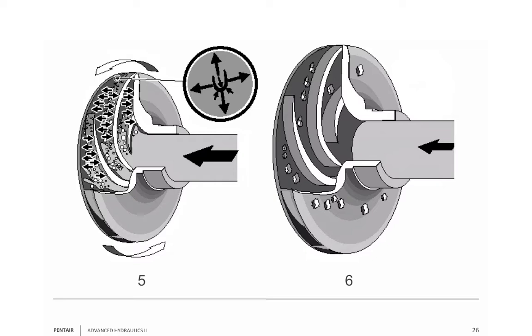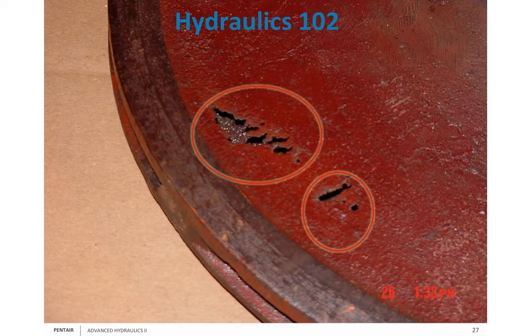Stainless steel and plastic are probably the best, and bronze is right up there with them. Okay? Now, how do you get the water moving that fast, you say? Easy. Open the discharge on the pump. Now, of course, if you don't have enough back pressure, what does it mean? It means that that vapor bubble goes all the way through the pump and out. Lucky you. You never see cavitation damage.